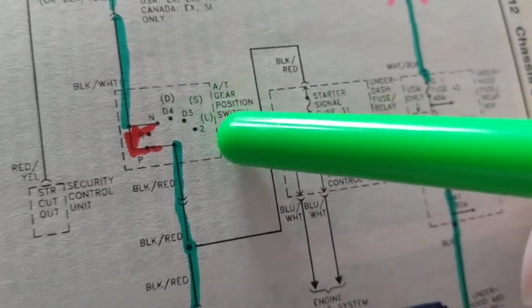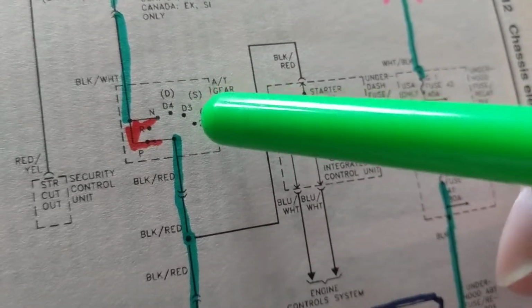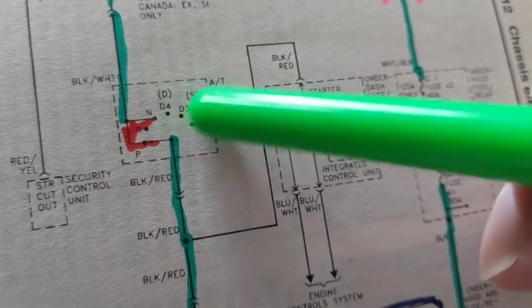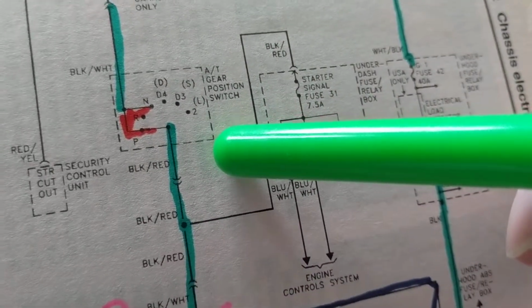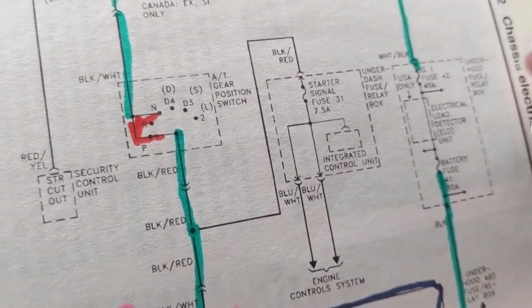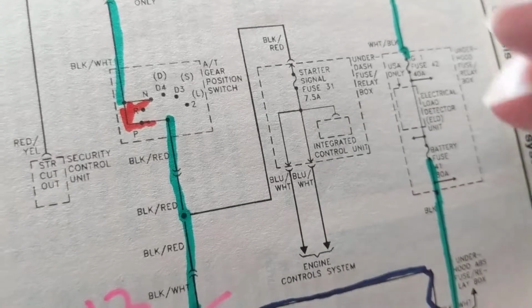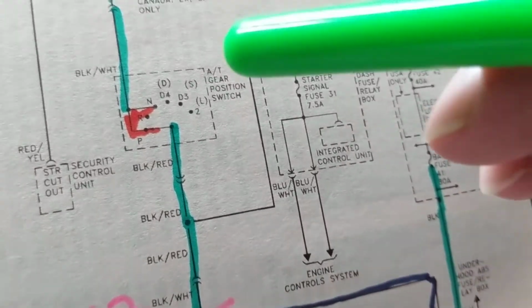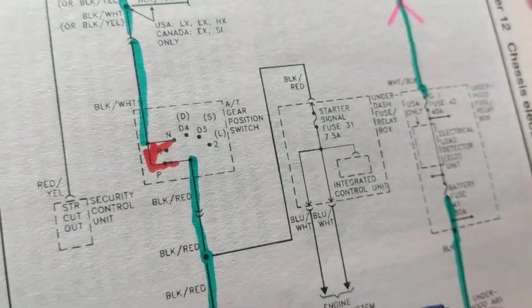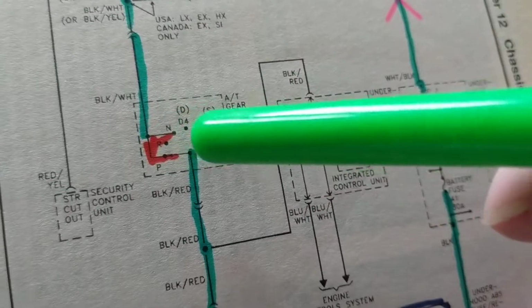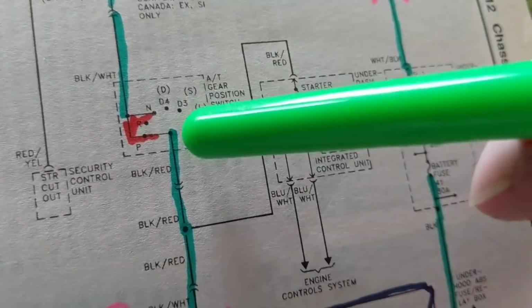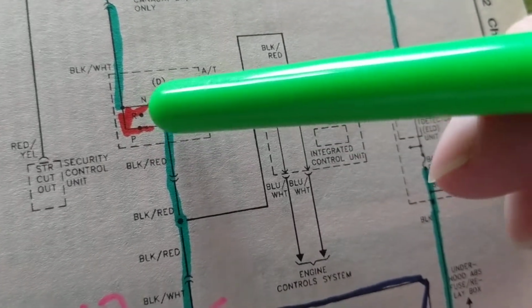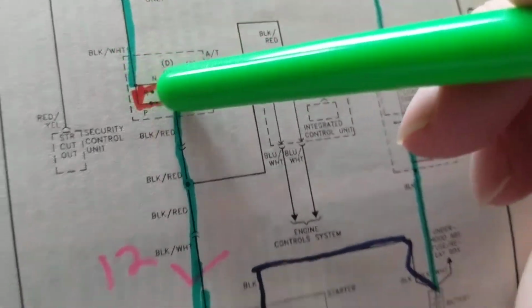Anything else, drive or another gear, the switch will not activate the starter motor, will not start the car. Same in Chevy, same in Toyota, Lexus, Camry, same idea. That's why if you know it in that one, you'll know it when you see it over here. That's why I have neutral connected and I have the park connected. So whichever it is, it's park.